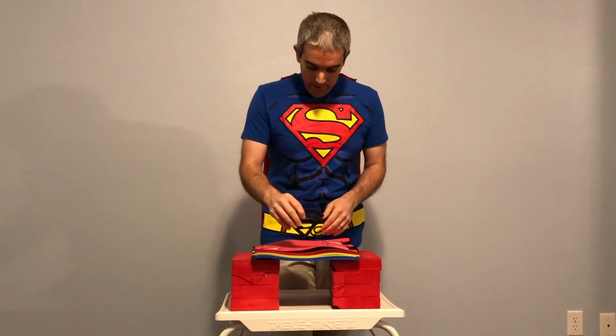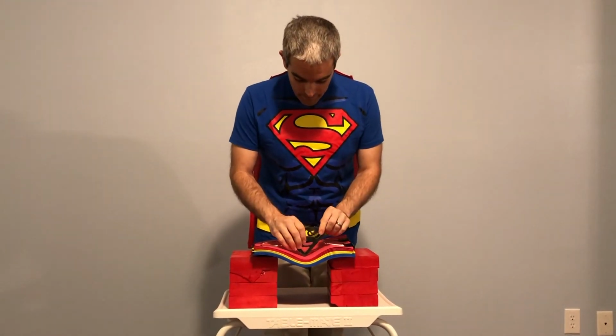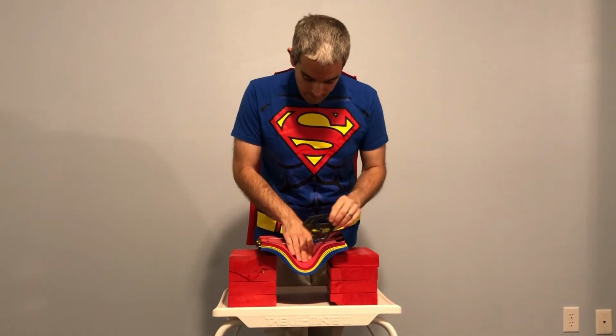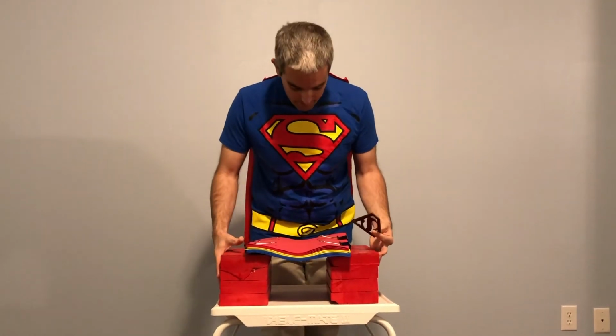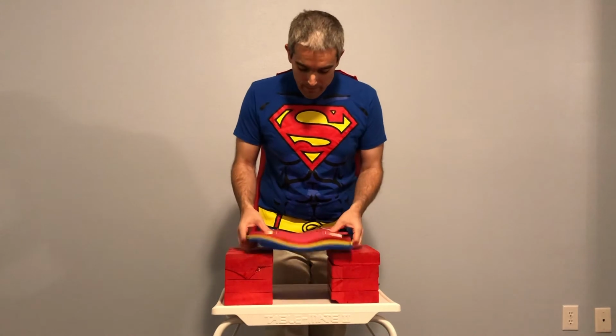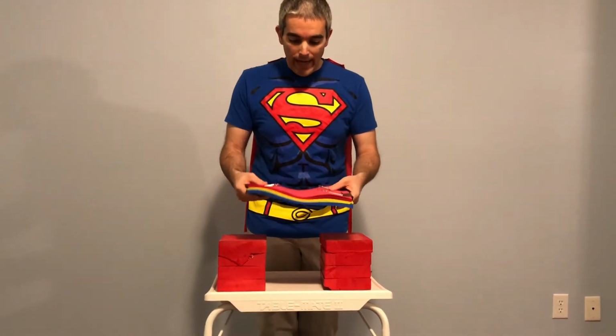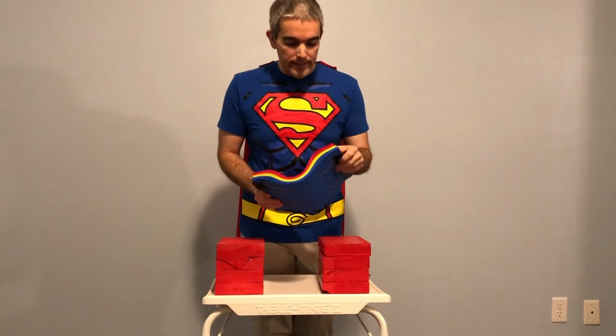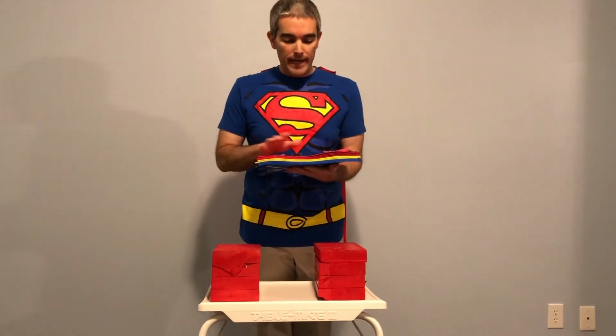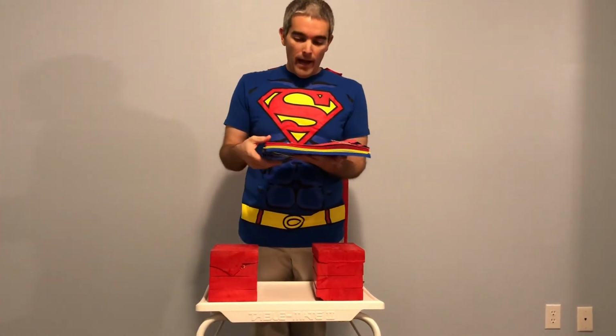Now if I go to put this point load on, I have to push a lot more, and I'm going to have to keep pushing quite a lot. You can see my supports are sliding here. But you can see that the composite system is stronger than the previous system. As it deflects or bends, the ends remain as one unit, so there's no sliding action. That's what happens in a system and how shear stresses work. Let's talk a little bit more about that and get this into your notes.